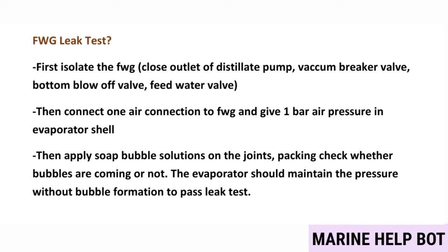This can also be carried out by maintaining vacuum inside the freshwater generator shell. Both methods are okay, but mostly the method followed is the one in which we connect an air hose, provide air and maintain a pressure of 1 bar.